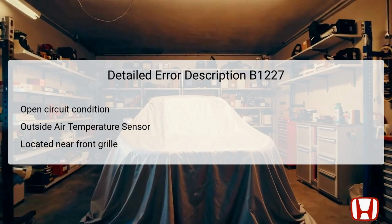An open circuit suggests a disruption in communication within the electrical wiring, potentially caused by loose connections, damaged wires, or the sensor itself failing. Identifying this fault is essential to restore proper function to the vehicle's temperature control system.